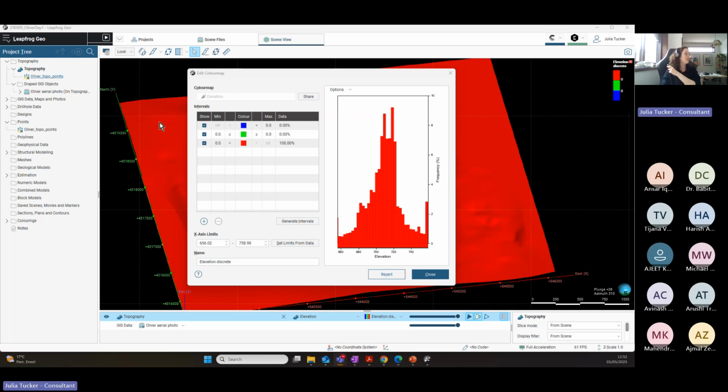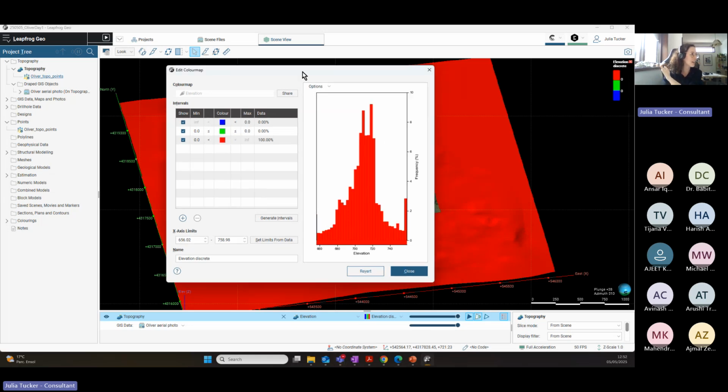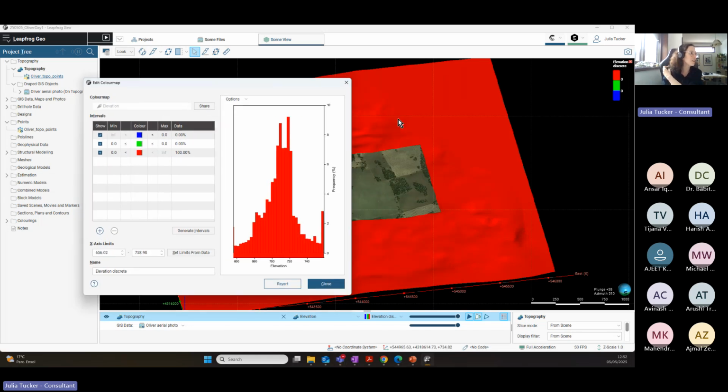I don't think so. So just carrying on, we can separate it as categories, as intervals. Right here, we can just input an option to see the histogram of the log. We can see the cumulative histogram, or we can change the bin width. What is the bin width? It is this width right here. So each column has a bin width of 3 right here. 3 what? 3 meters, because we are talking about elevation.